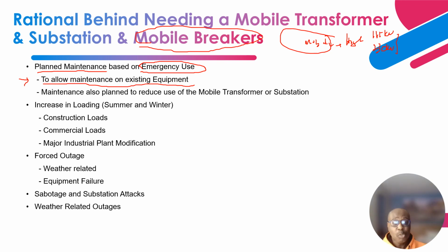Especially if you are performing a major maintenance on a transformer, that is typically a 6-year interval, and that major maintenance can take about 2 to 2.5 weeks, to do all the disconnection, maintenance testing, then evaluating the results, and after the results are good, reconnecting and energizing. That takes about 2.5 weeks.